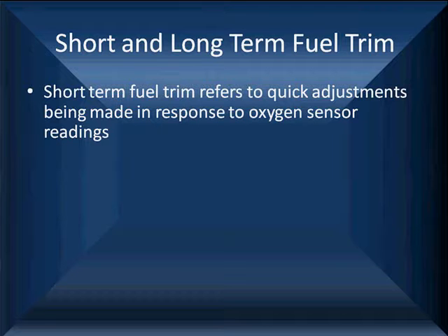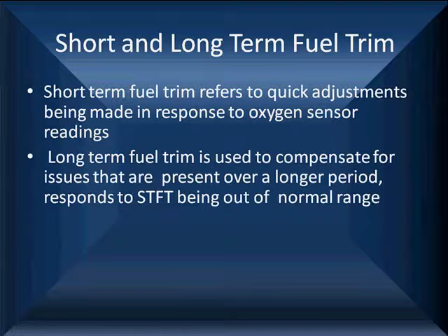Short-term fuel trim refers to the quick adjustments being made in response to the oxygen sensor reading. Stop and let that sink in. It's responding to the oxygen sensor reading. We'll show you how it happens later. Now, the long term, as we said before, is used to compensate for issues that are present over a longer period of time. It responds slowly to short-term fuel trim being out of the normal range.